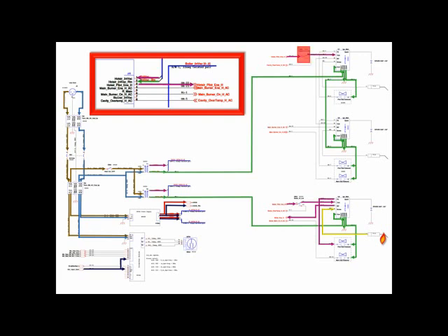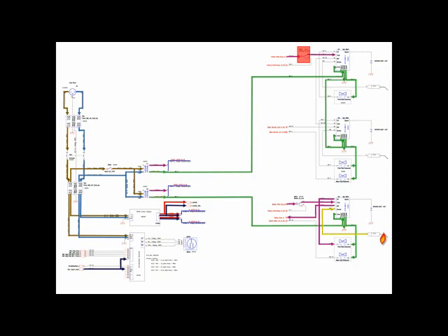If the cavity high limit trips, the voltage is removed from the ignition module and sent back to the relay board to J4 pin 8. In normal operation, the cavity high limit sends voltage to the primary hot air